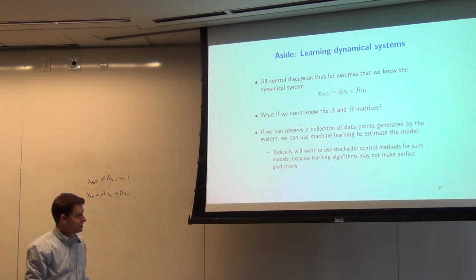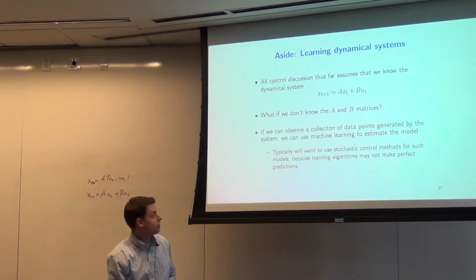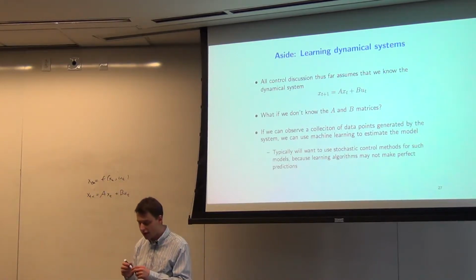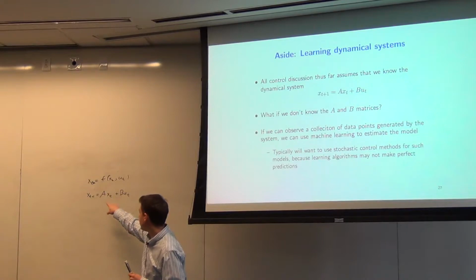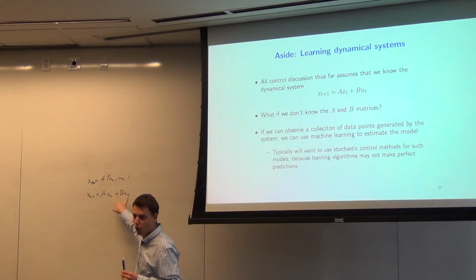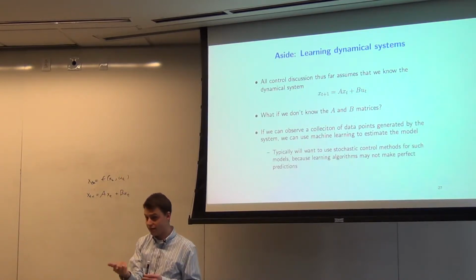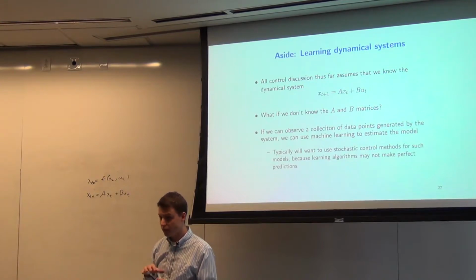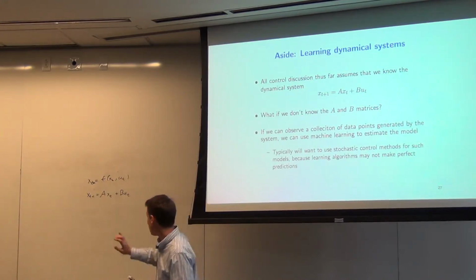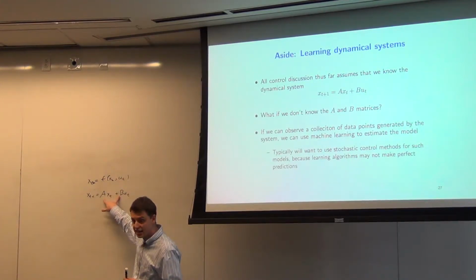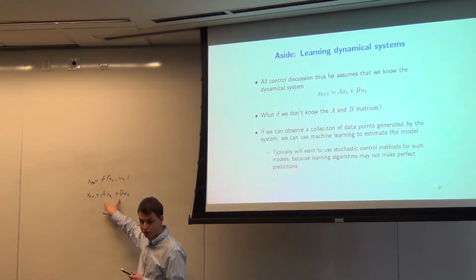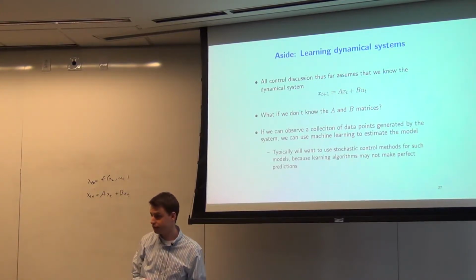And basically everything except PID control assumed that we knew what these, say, A and B were. For LQR, you have to plug A and B into that LQR command in MATLAB in order to get a controller out. For MPC, you have to put these two matrices into the optimization problem itself for it to solve. They all require that we actually know what they are.